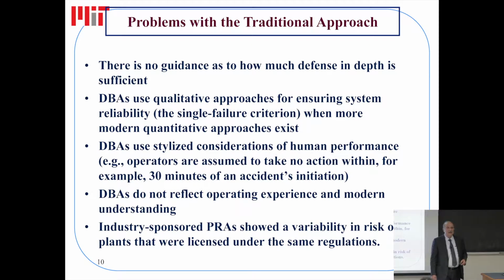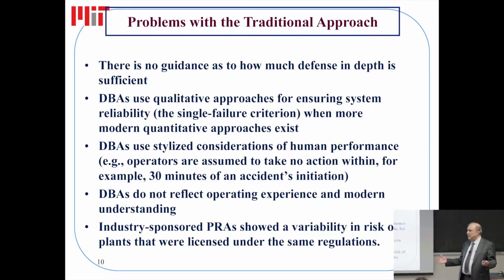I gave you already the example of large pipes. They just don't fail. And yet, if you want a license, you have to show to the NRC staff that if there is a guillotine break of the largest pipe, and loss of offsite power, and the single failure, you can still tolerate it.